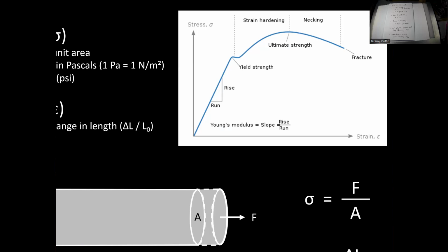But what if you take a paper clip and clip together like 100 papers and then take the clip off? Now isn't it all permanently warped, deformed? Well, that's what happens beyond this yield strength, beyond this yield point. Beyond the elastic zone, that's permanent deformation. Which, by the way, we're done with concrete by this point. Concrete just goes push, push, push, push, push, and then bam, it just ruptures right here.